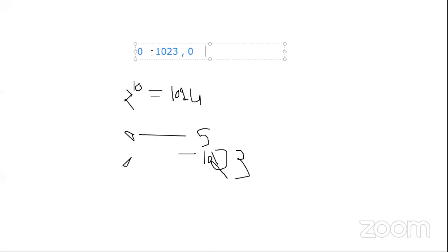Okay. Now we have to convert back to 0 to 5 volt again. Just suppose I show 5 volt over here, it is read in the format of 1023. So I'm going to make it reverse. The 1023 value we are reading is 5 volt in the Arduino, because we are going to convert this analog 10-bit value again into 5 volt.